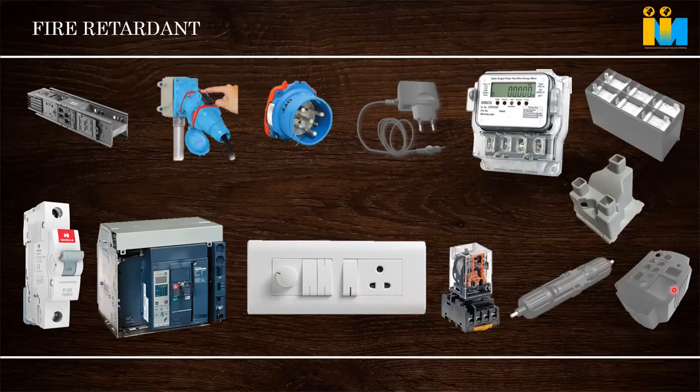And this is a back case of an electrical torch or something, a chargeable torch. Here, on the backside, there will be a heat sink. The temperature rise will be something around 90 degrees, and electrical property should also be there. So we use polycarbonate with flame retardant, and polycarbonate can withstand, as I told you, 115 to 120 continuous use temperature.